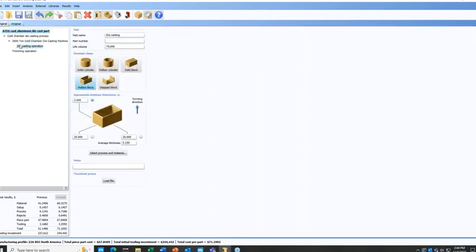What I'm going to do is make a copy of this analysis. Here in this copy, I'm going to turn off dynamic costing, and then go through and specify information for all of the inputs that were hidden. So for example, my batch size, let's say, is 12,000 parts. My maximum thickness is quite a lot different, so it's 240 thousandths in thickness.